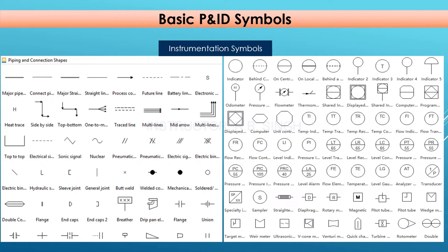Similarly, if you are doing the magnetic flow meter, you need to know the magnetic flow meter by its symbol. So in short, you must know all the symbols of flow meters, valves, temperature instruments, pressure instruments, switches, level instruments, analyzers, detectors, so that whenever you do the engineering or prepare any document, suppose the instrument index, you can decide what type of instrument it is. That means you need to know the symbols. So these are the symbols indicating any particular instrument.